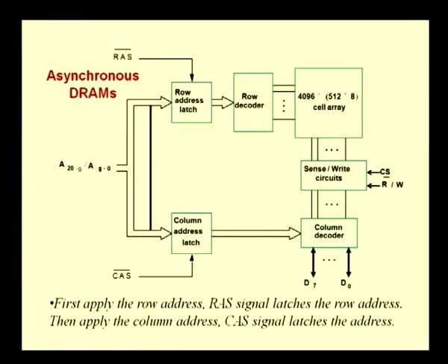When you have many address lines that need to be given to a particular chip, that occupies some space. So, to optimize on that, we divide the entire addressing into row addresses and column addresses and use the same lines to first send the row address and then send the column address.